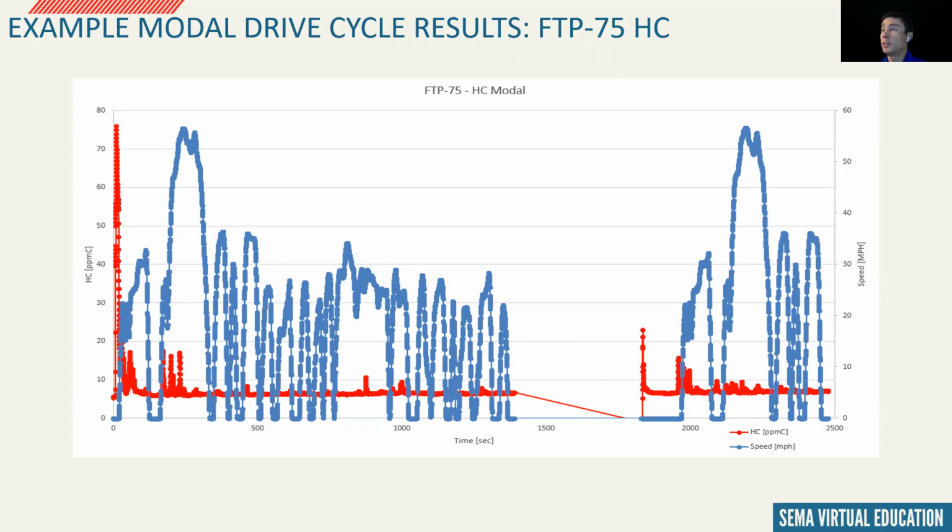You will usually get a little spike during the hot start as well because closed loop control is not available instantly during a hot start either. Closed loop should enable very quickly though during a hot start, maybe 5 to 8 seconds after the start event.